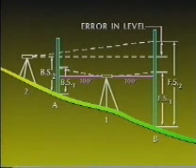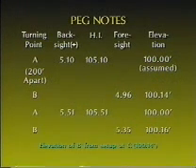Any difference in the 2 elevations is the result of misalignment of the instrument crosshairs. This mechanical error must be adjusted out of the instrument by actually moving the crosshairs in the level scope up or down to make the foresight FS2 yield the same elevation for point B as FS1, thus eliminating the error. As an example, the following illustration details the computations used in pegging a level.